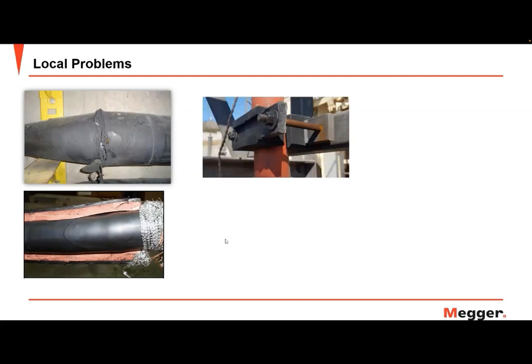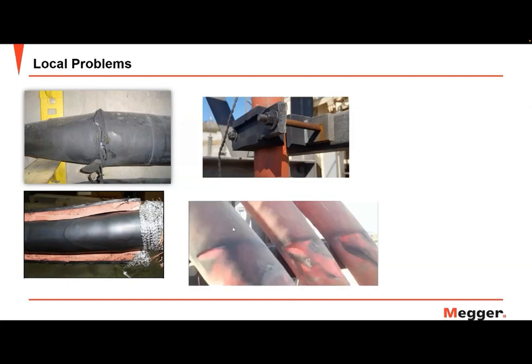So you just have a cable clamp to hold the cable in place. Now these are supposed to be specified to a certain torque. You shouldn't over torque these to cause damage. Now in this case, what had happened was that there was too much force put on these and it ended up causing damage to the cable. If we look, we can see all three cables were over torqued and therefore permanently damaged.